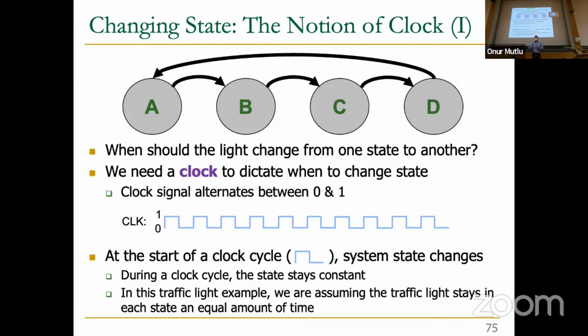This will become much more clear when we talk about timing and verification. But this clock cycle is really important so that you can design your combinational logic so it can finish what it needs to do within a clock cycle. So in the Swiss traffic light example, we assumed it's 5 seconds, right? But when you design a microprocessor, you usually have a target. Okay, I'm going to have a 10 gigahertz machine. 1 gigahertz is 1 nanosecond, so 10 gigahertz is 0.1 nanoseconds.